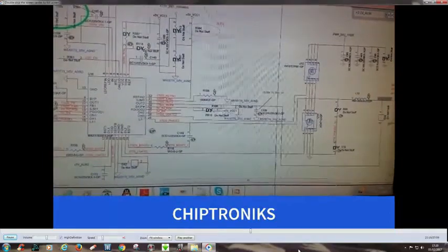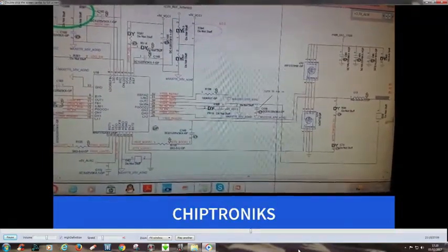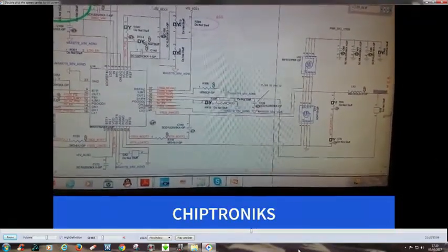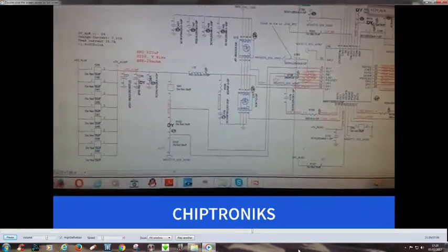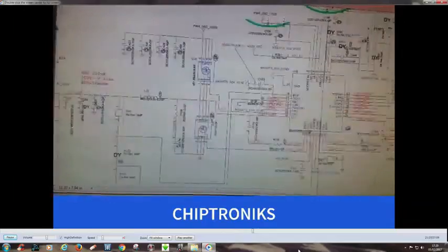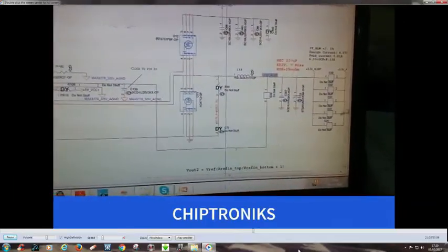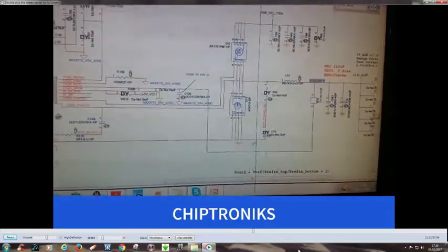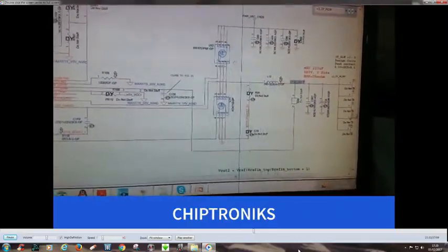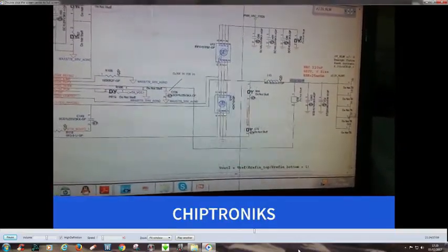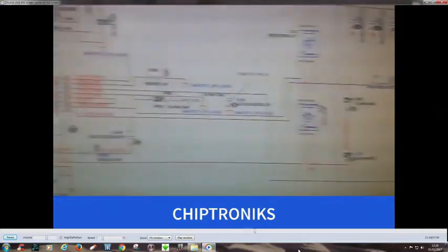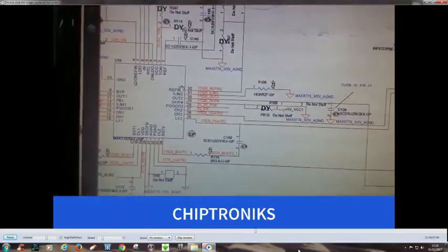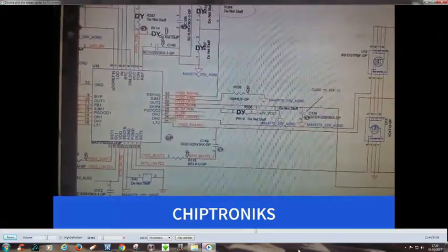And this driving voltage will get enabled only when this regulator, you can see this is a dual regulator. One side it is generating plus 5 volt, another side it is generating 3 volt. This MOSFET will switch once it gets the driving voltage at the gate,